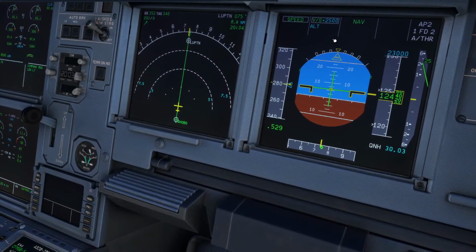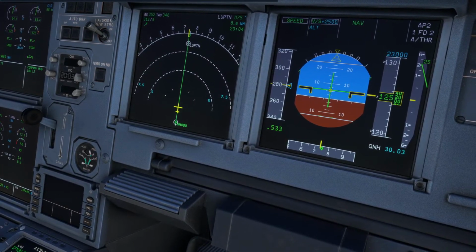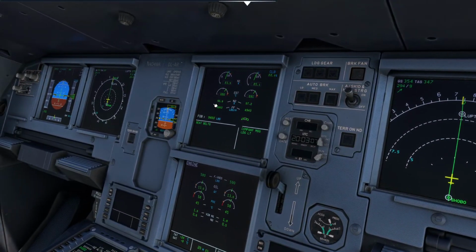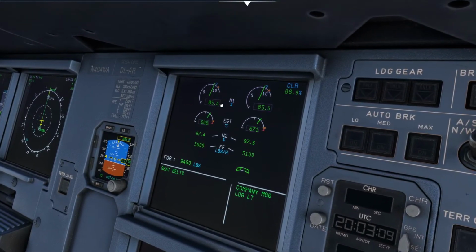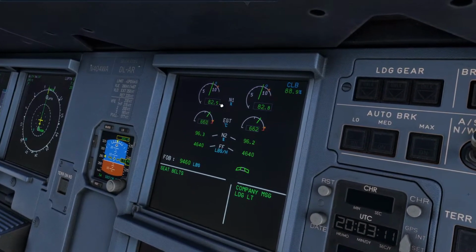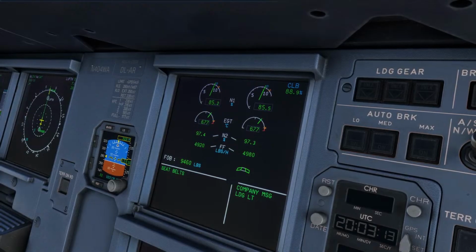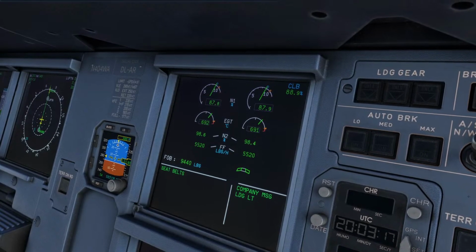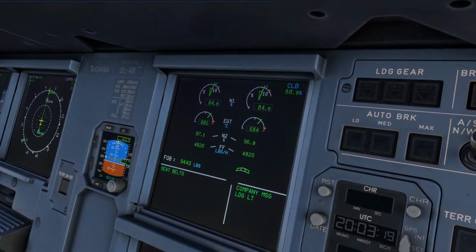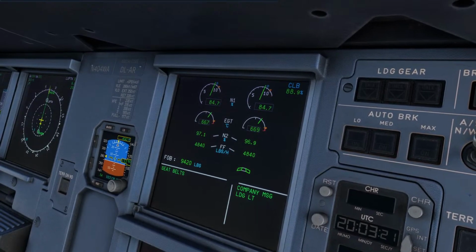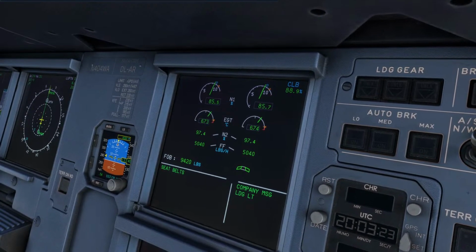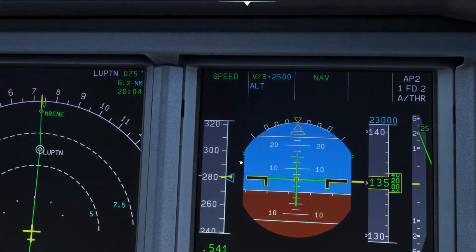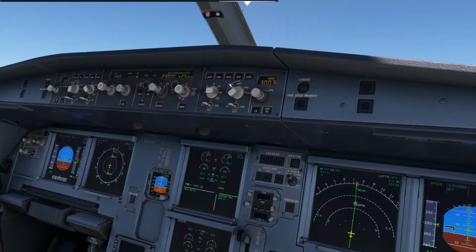The airplane is still going to try to maintain 280 until there's no more excess thrust, right? So if you notice, the autothrottle is going to vary the thrust, and it'll try to maintain that 280 until it's like, okay, I'm balls to the wall. Now I'm just going to maintain 2,500 until we get too slow. Does that make sense? It's always going to prioritize vertical speed, always, which is why they don't want you climbing via vertical speed, because the airplane's always going to do that.